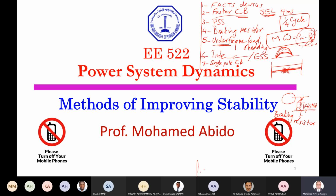If you trip only one phase, you have unbalance, and this will definitely affect the induction motor performance. You have a lot of harmonics and vibrations and so on. There are some challenges for single pole switching, but if we focus on improving the stability, yes, it will harm the system in terms of harmonics, vibrations, heating, and so on. But this is for a very short time where we need to keep the system stable. We need to preserve the system stability.